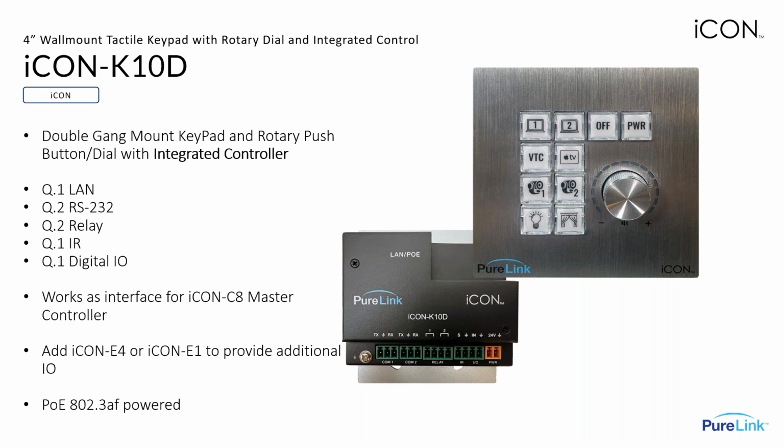And as you can see on the back here, this is also PoE and has LAN communication alongside 2 RS-232 ports, 2 relay ports, 1 IR port, and 1 digital I/O. This can also work as an interface for the iCON C8 master controller, which we will get to in a later slide. And you can add the iCON E4 or E1 to provide additional I/O ports.